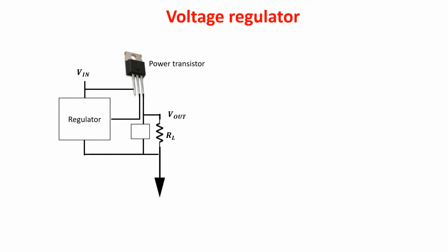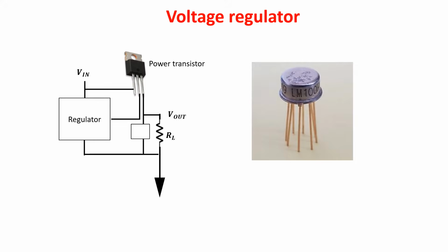Even Widlar, in the paper Designing Positive Voltage Regulators of June 1969, writes against it. First, there are no standard multi-lead power packages, he said. For example, the LM100, an adjustable voltage regulator, had 8 pins and there wasn't an 8-pin power package. Second, integrated circuits necessarily have a lower maximum operating temperature because they contain low-level circuitry. This means that an IC regulator needs a more massive heat sink. Third, the gross variation in chip temperature due to the dissipation in the pass transistor worsens load and line regulation.